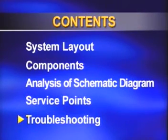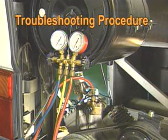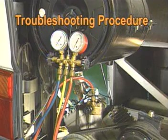At last, we would like to explain troubleshooting and common problem types of the roof-on air conditioning system. When the warning lamp turns on, or the customer complains about cooling performance, diagnose the problem by using a manifold gauge. The checking procedures are as follows.